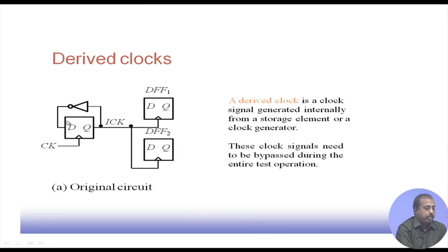So it will be generating the output continually: whenever D is 1, this will become 1, then this is 0, and this will become 0, but that will happen at half the clock rate that we have here. So, this is a clock divider type of circuit, and then this derived clock is given to the 2 D flip flops. Okay. So, this is the derived clock circuit.